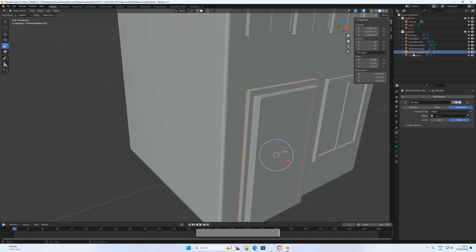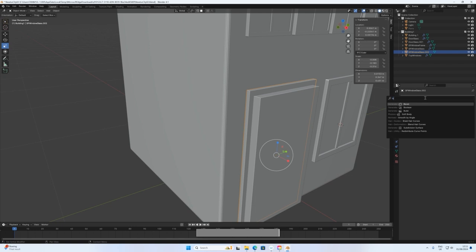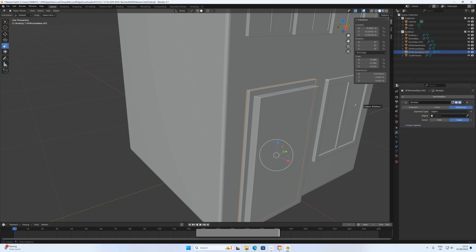Oh, it has a boolean added to it because when I duplicate it. So window, yeah, let me just remove that because when I duplicated that, it had a boolean in it, but now there is no cutter. So this boolean here, I don't need it. So I'll create a new one, add a modifier. I could use the same one and just change the object that's cutting, but you know. Okay. And that one is the door glass. Okay, so I can apply this boolean here.